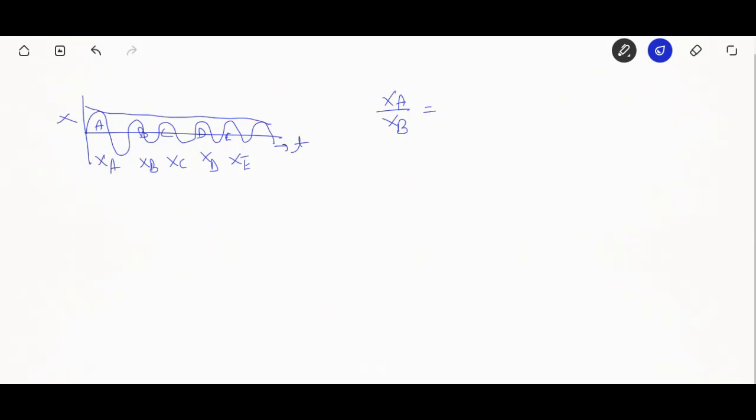Because we drew the graph for critical damping and overdamping, it showed a steep decline in amplitude, right? So there is no periodicity in that sense, so there is no concept of successive amplitudes like that, right? Now, the logarithmic decrement is for the underdamped case only, right? This is what we need to keep in mind here.